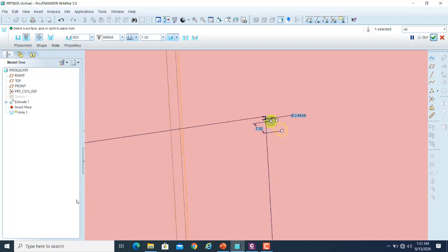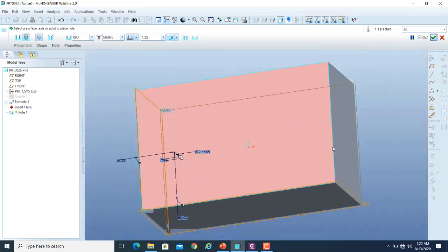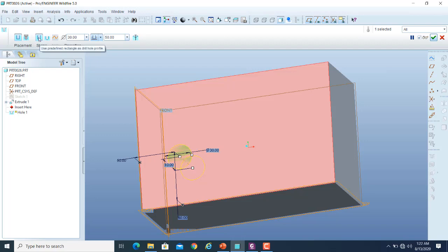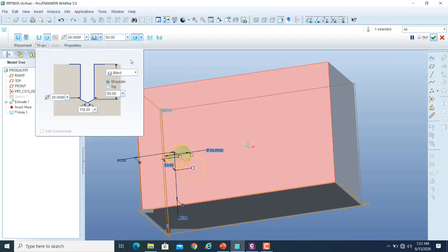So this is the standard option. You have two options basically: the standard hole option and the simple cylindrical hole option. Within the simple cylindrical hole option we have further the flat and the conical end options, and then within the conical option we have these counterbore operation and countersinking operation options.